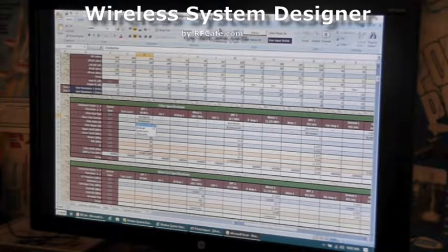And for filter types, you can choose the null, which is the dashes or no filter. You can do a brick wall, which is just a flat response in the pass band and infinite rejection in the stop bands.